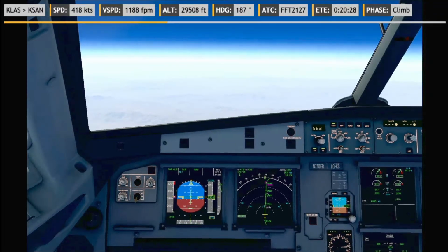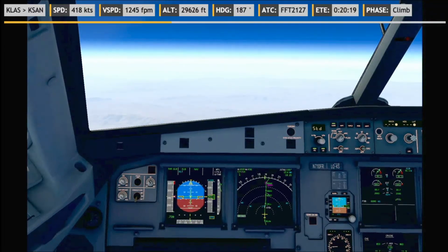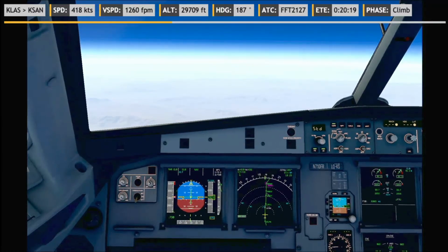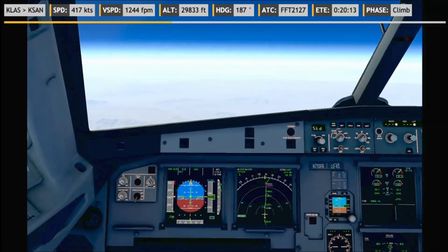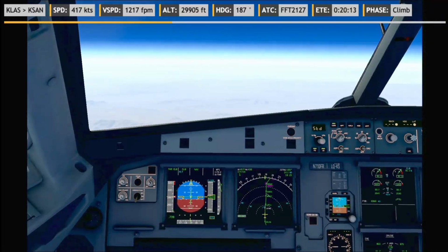Briefing, so flying the RNAV Yankee approach, runway 27 in San Diego, with frequencies for comms are not required. Final approach course is going to be 275. It's a GPS approach, so no primary navaid required. Although we might want to have Mission Bay DME up.